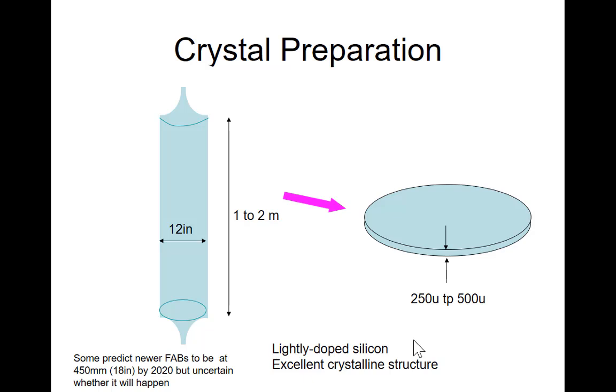After this ingot is made, you also notice that as you are pulling up, the ingot on the top and the ingot on the lower part have different gravity load on it. So the crystal structure in it actually has different stress built into it, and it's not uniform.